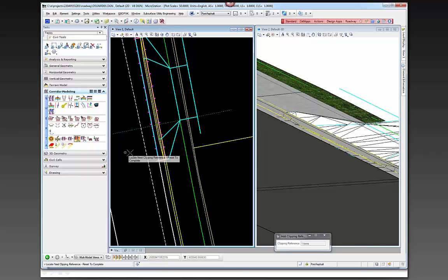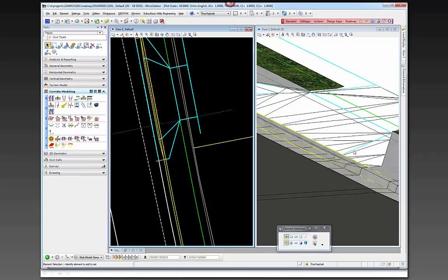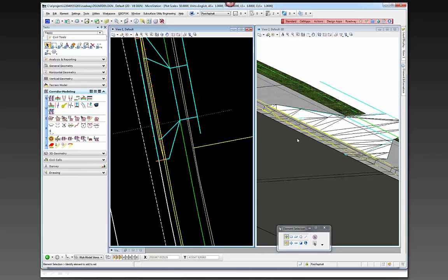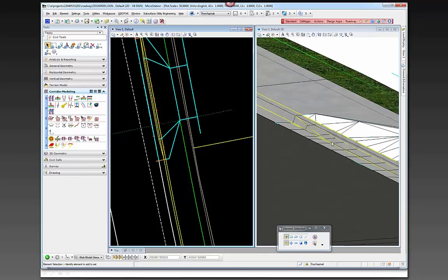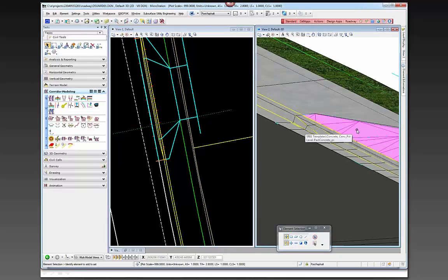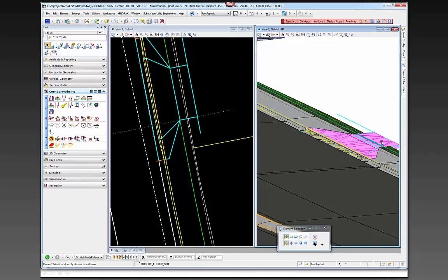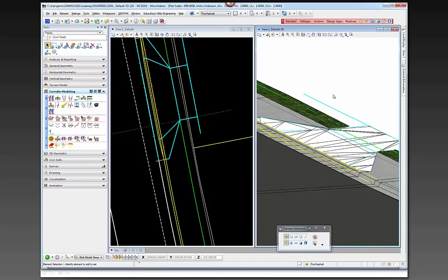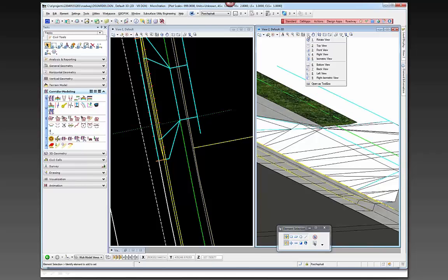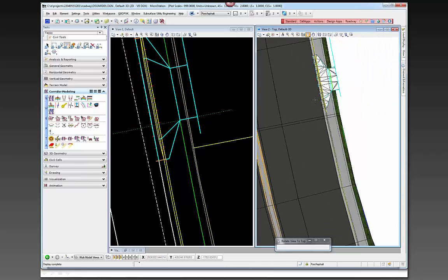This civil cell works only in a perpendicular situation. So if you had a skewed urban driveway, the civil cell wouldn't work. You'd have to go in and build that on your own. So now you see the actual transition here, the curb going down, and this is the actual driveway, concrete placed in there as well. It just shows in white, but there, and you can see from a top view how that 3D driveway gets placed in there.